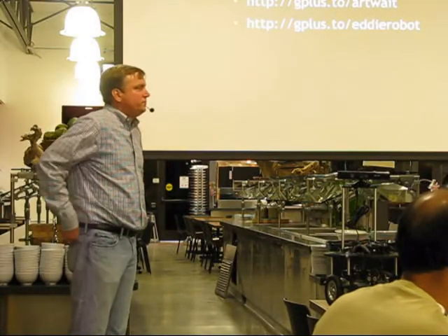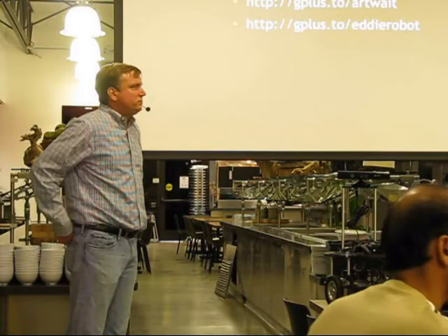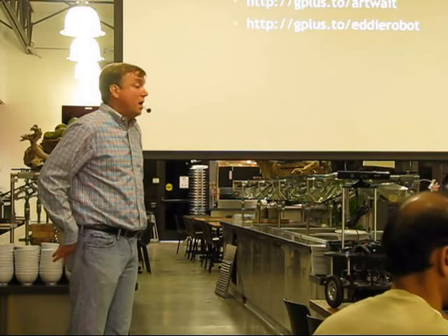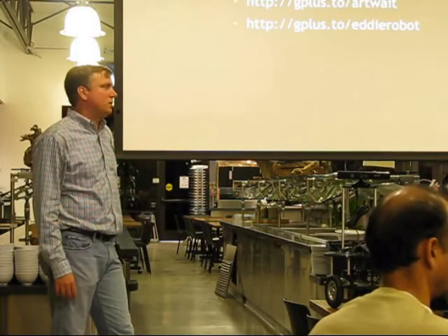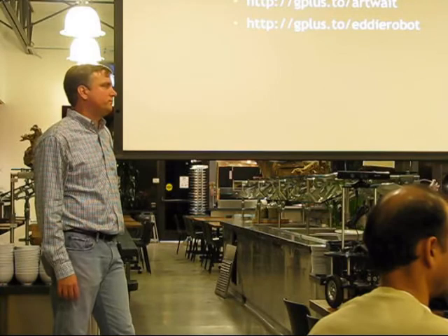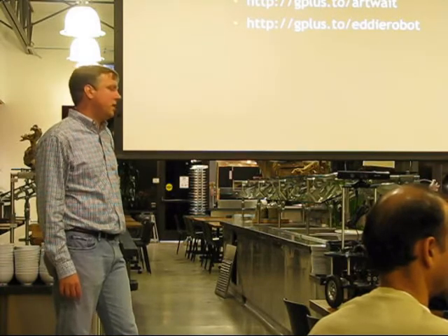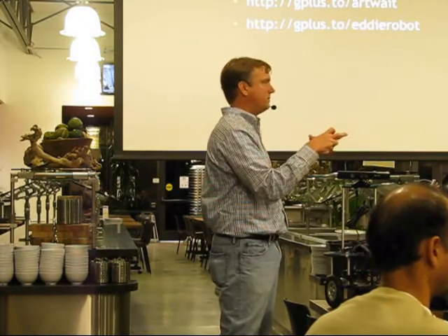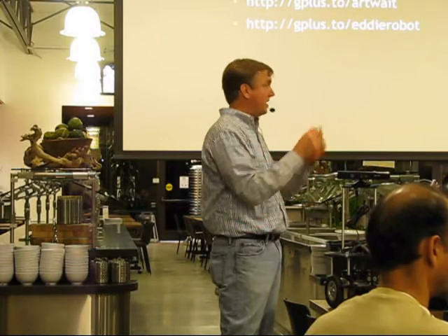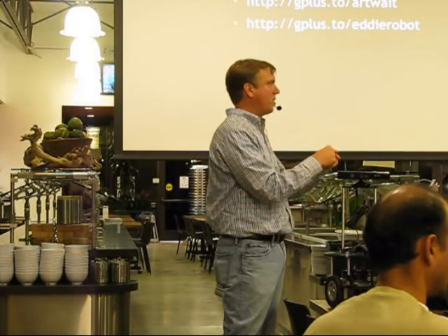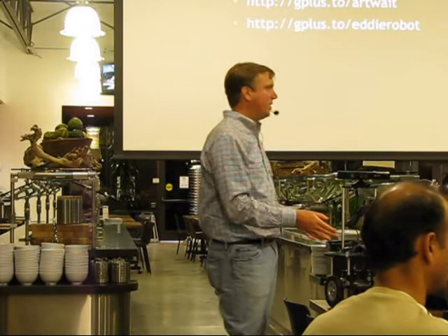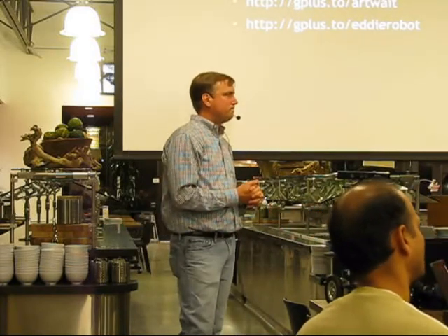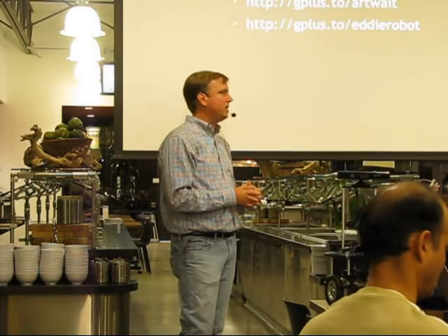So the computer sends Bluetooth to the NXT bit of data. How does it talk to the propeller? That's USB. So wouldn't that make it a serial stream? Are you taking advantage of the cogs in the propeller that way? Yep. The board here, by the way, is not just a propeller. It's a full board that Parallax provides, and it has a propeller as its processing core, but it's got I/O on there for the sensors and for the motor drivers and all that. Does RDS talk back and forth to the propeller, or does it just compile and download? It's no compiling and download. Okay.